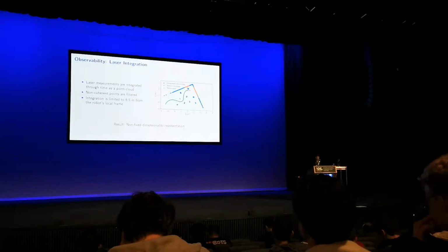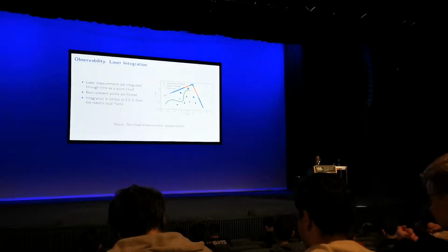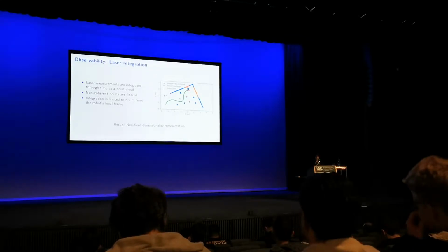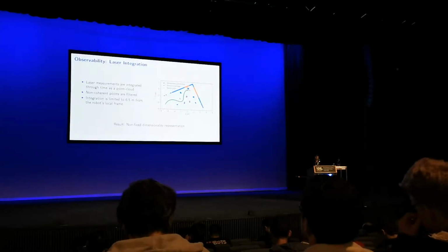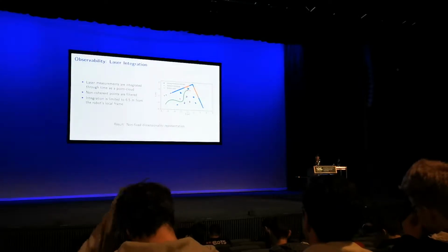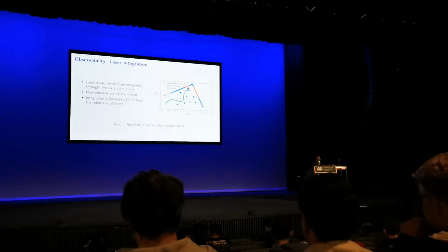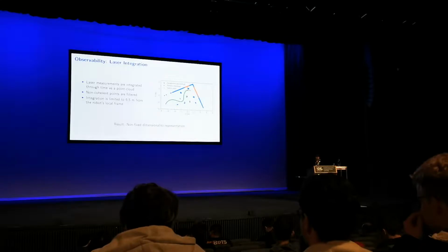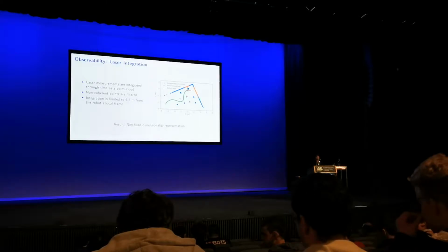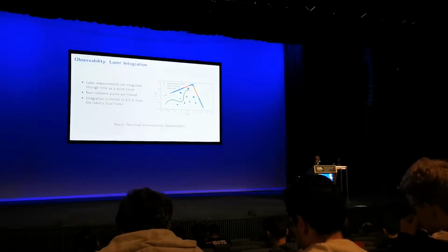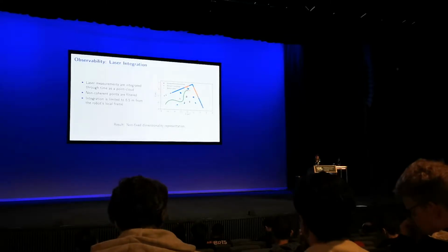And what we did to tackle that issue was to go through a naive approach, but just integrating laser range measurements as a point cloud through time, and filter non-coherent points, so the policy will be able to actually react to dynamic obstacles, even though it will be trained using static obstacles. And we actually limit the integration of such representation to only 6.5 meters away, since otherwise odometry will constantly integrate errors in time.